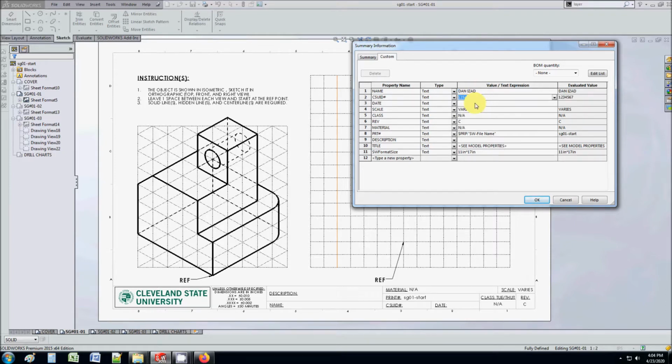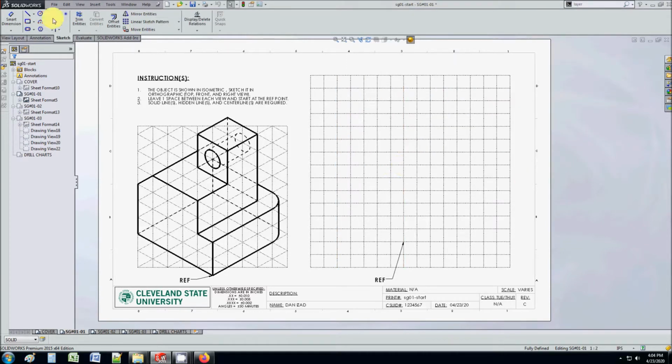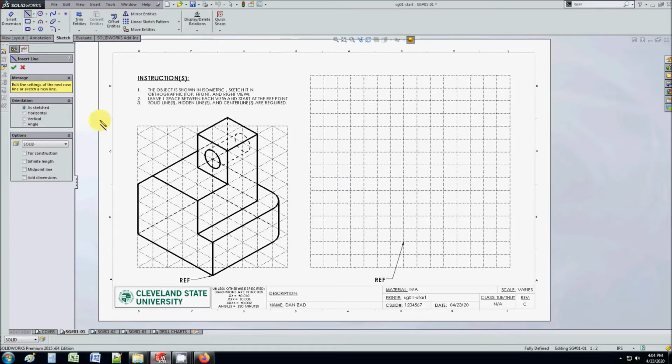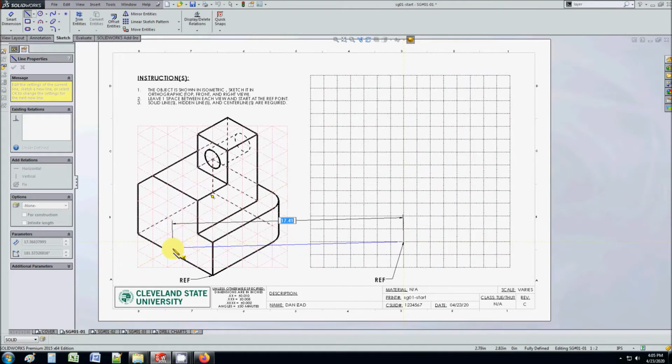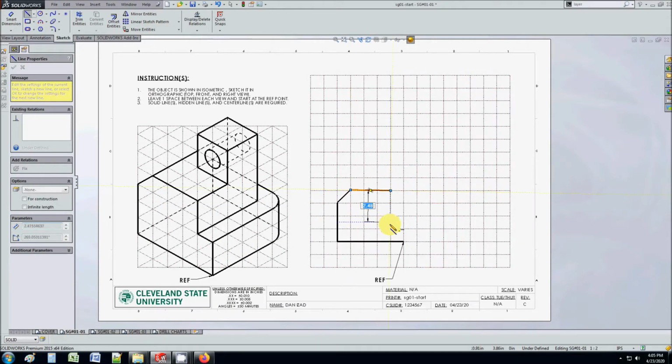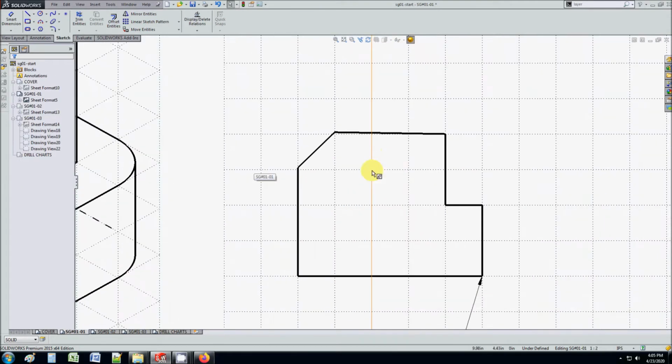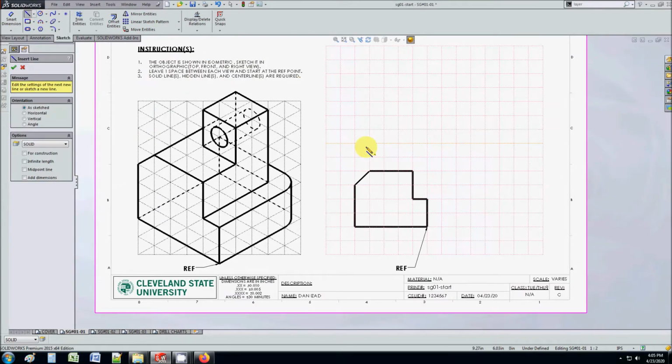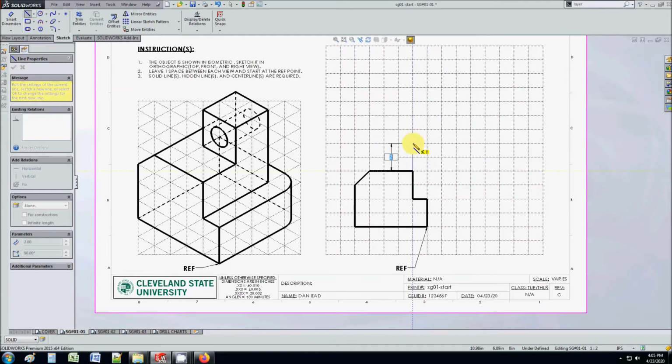So make sure to fill all this. There it is. So I'm gonna start drawing. Okay, you're gonna count the cubes. 1, 2, 3, 4, 5. Okay, 5, 3. Alright, so I'm just drawing the projection. Okay, and that's what you're gonna do on the exam. Like I'll give you an isometric and draw the projections. Okay, so there's that. Then I'm gonna add a little cube on the top.